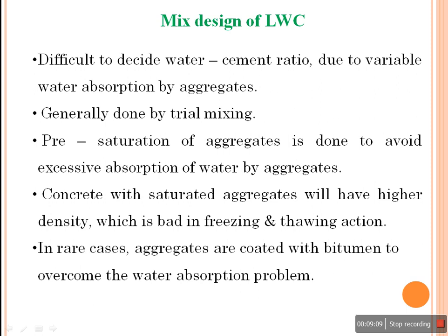Pre-saturation of aggregates is done to avoid excessive absorption of water by aggregates. Concrete with saturated aggregates will have higher density, which is bad in freezing and thawing action. In rare cases, aggregates are coated with bitumen to overcome the water absorption problem, because bitumen is a very good repellent to water.